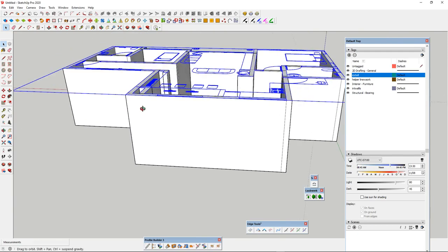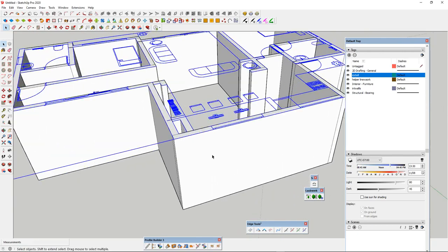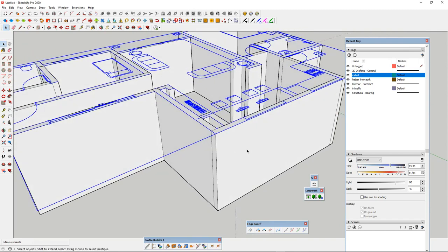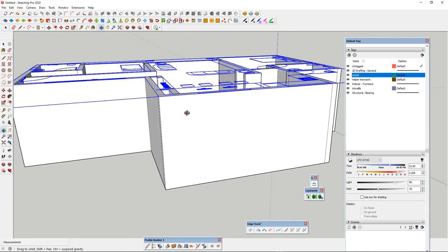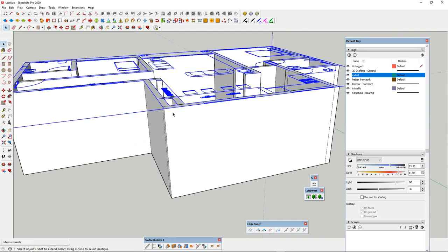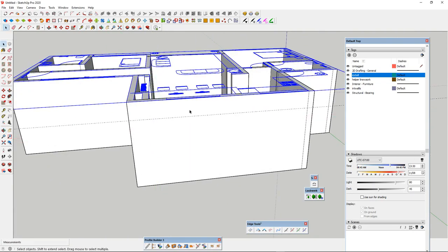Now, as you probably know, if you're in the construction industry, design industry, most houses have a ring beam going around the house. So you want to measure what height that beam is at, and use your tape measure. Choose the tape measure tool and move it up and type that height. In this case, it's going to be 2400. So that's going to be the level of our beam.